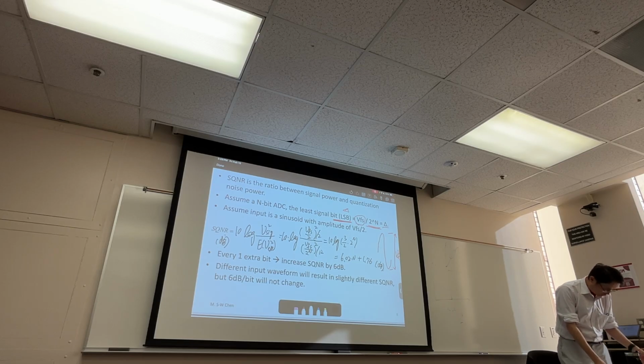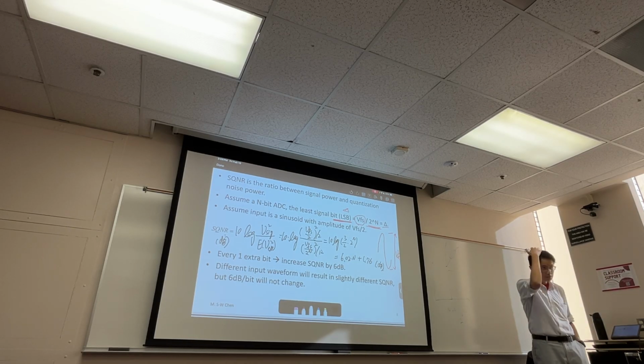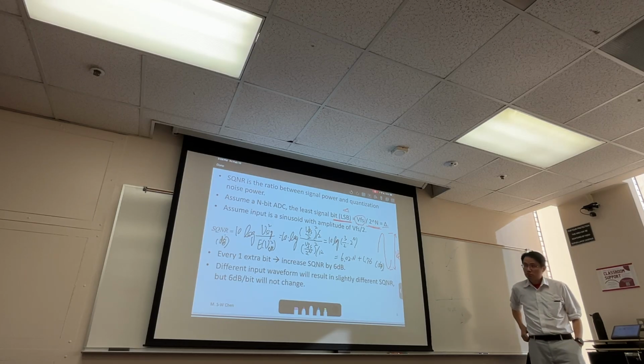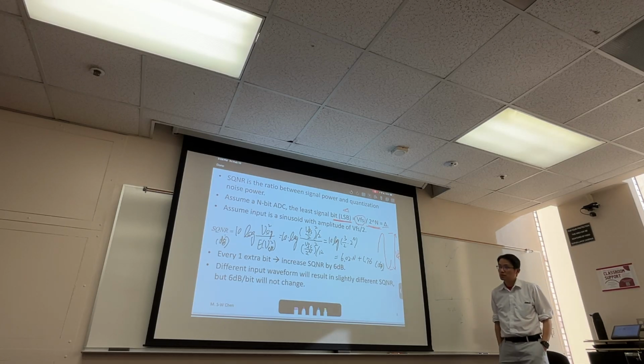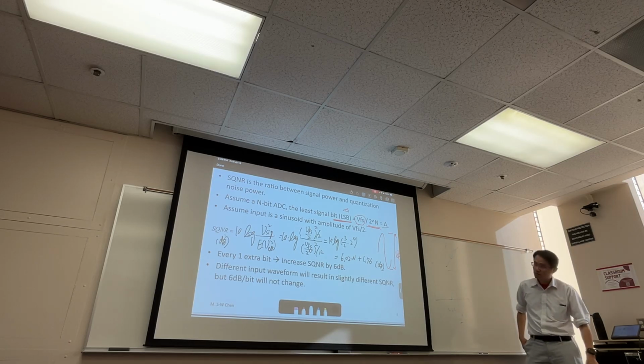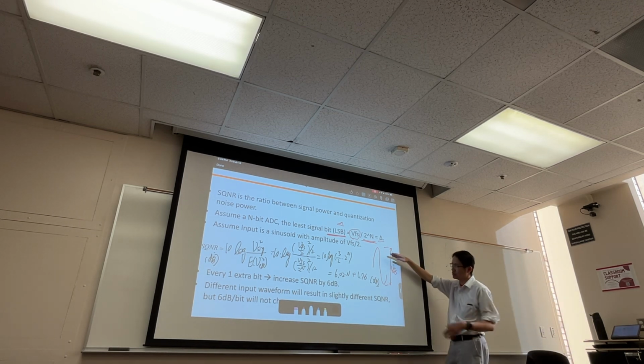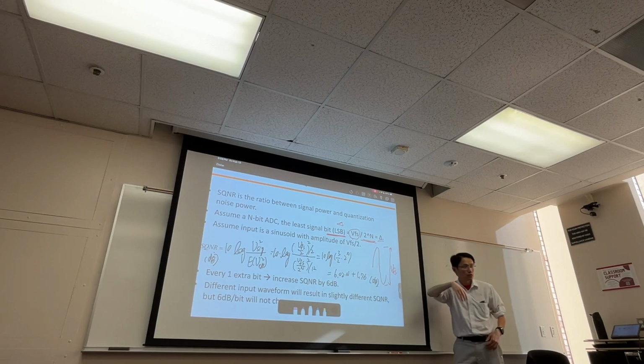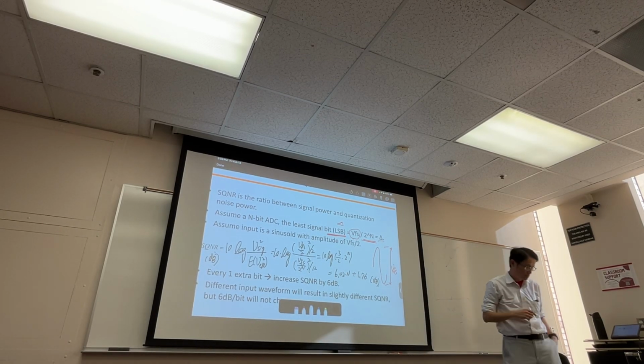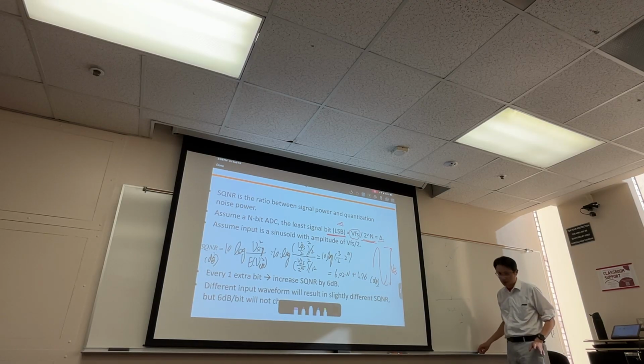Okay, that's a good question. Any other question? Yes. Here it looks like it really doesn't depend on the full scale, whatever your full scale voltage is, right? Because it just cancels. Yes. But before you said that if your full scale voltage is comparable to the quantization step, then you can't really generalize your quantization error as noise. Yeah, if your input is so small, yes. So imagine if it is smaller, the SQNR still depends ultimately on the full scale voltage. Yes, it does. Actually that's a very good question.